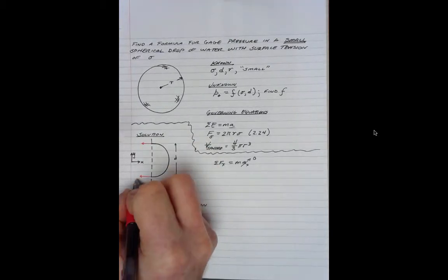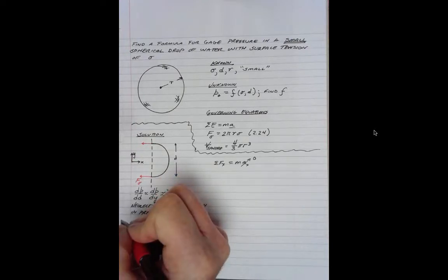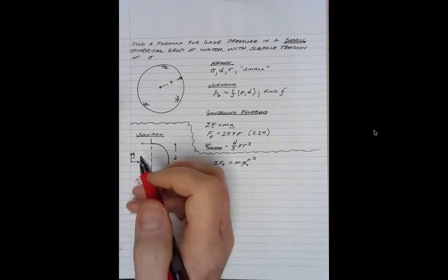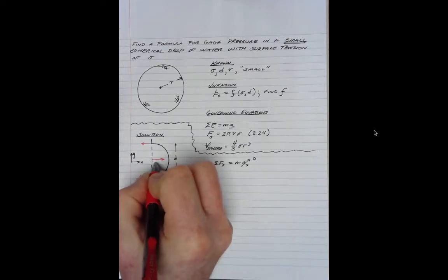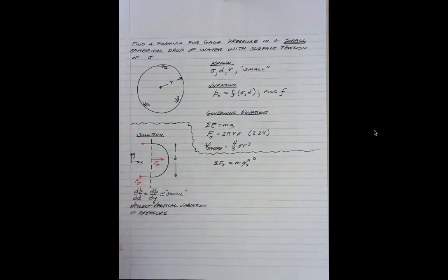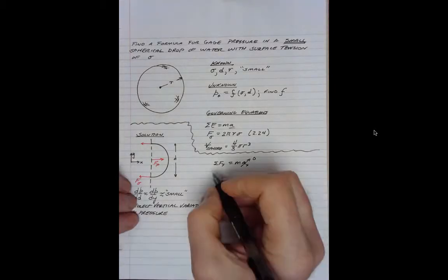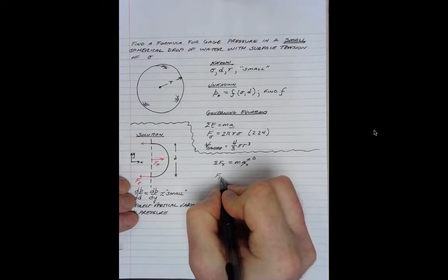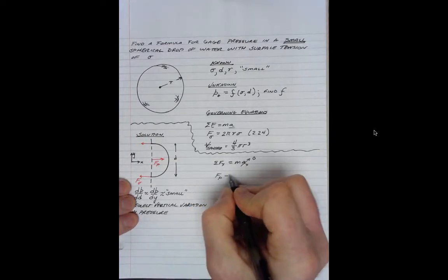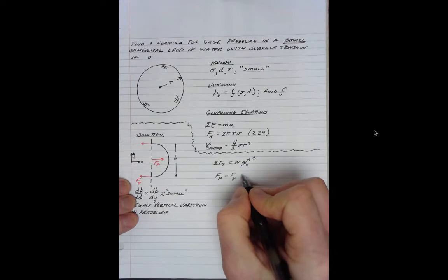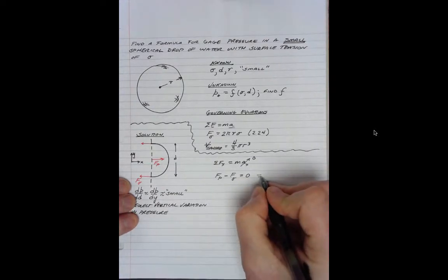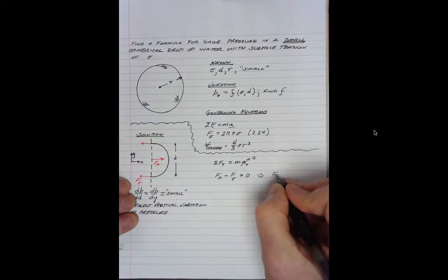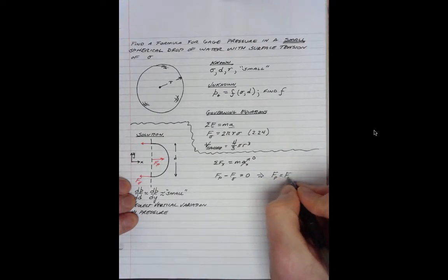So this is the tensile force from the surface tension of the drop, and then there is some pressure force from the other half of the drop pushing it in. So we have F sub P in the plus x direction minus F sigma in the minus x direction, and that equals 0. From that we conclude that Fp equals F sigma.